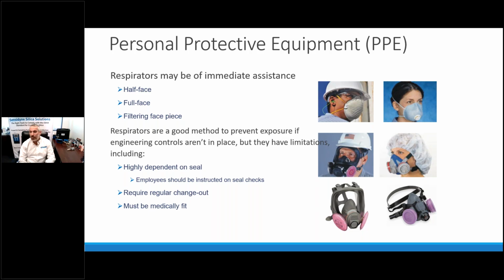Know what type is appropriate for the work you're performing. Know what the protection factors are for the different types of respirators, and understand that in heavy environments, not only might the exposure to inhalation be an issue, but there might be concerns with ocular exposure.